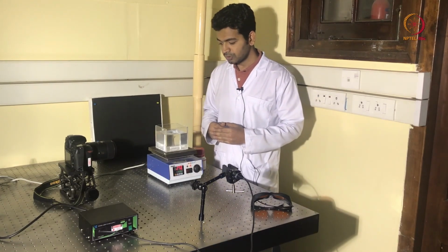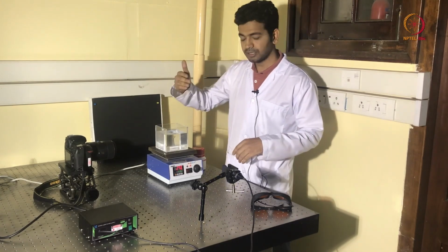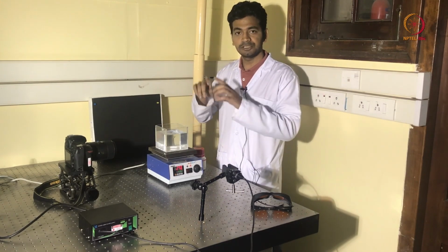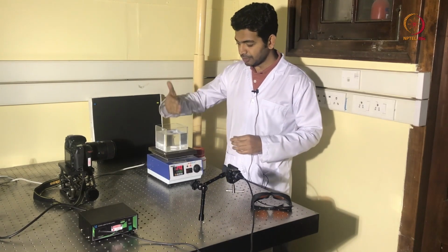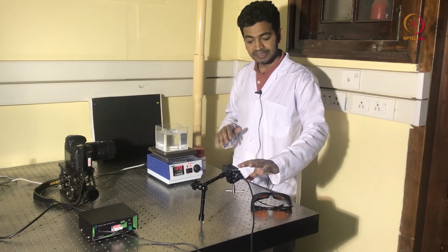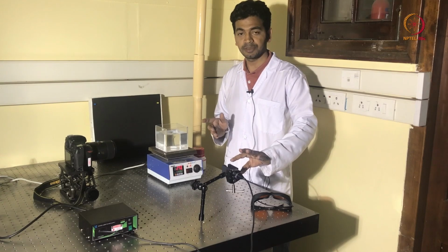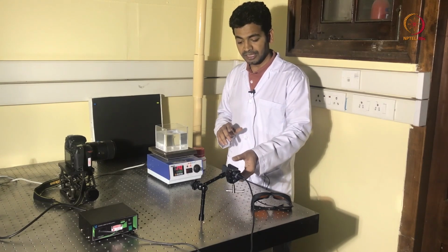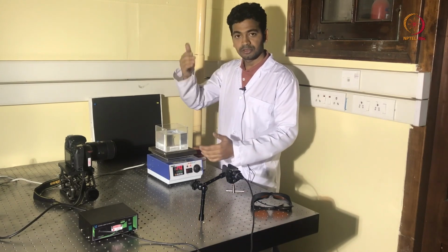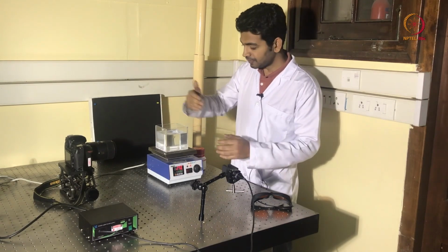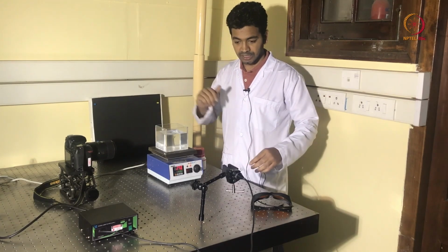Now to do particle image velocimetry, you need to illuminate your plane of interest in which you want to see how tracer particles are moving. So to illuminate a particular plane, I have kept a laser here and then a cylindrical lens, which I have earlier demonstrated in the previous video. This cylindrical lens transforms a cylindrical beam of light into a diverging sheet of light. That sheet of light illuminates particles in a particular plane. So let's turn on the laser.